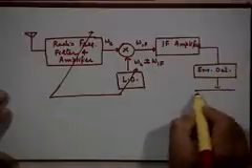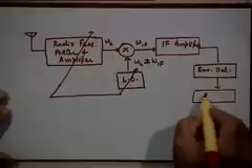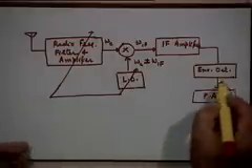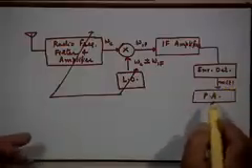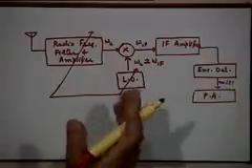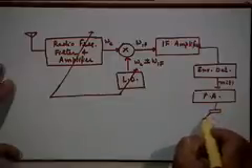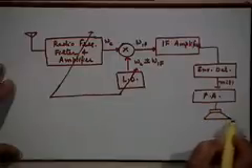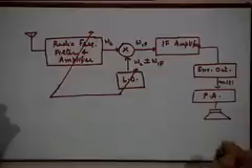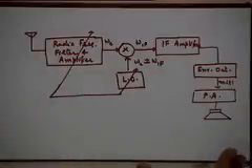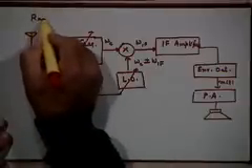followed by a power amplifier, which is where most of the distortions are likely to arise, because now you have the message signal here which you want to power amplify before you drive it into a speaker or whatever output device you have, and this can go to, let us say if it is voice or music, the speaker. That is typically the block diagram of a radio receiver, right. So that is a typical radio receiver.